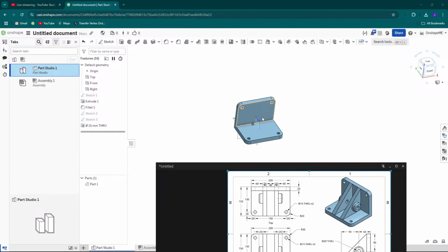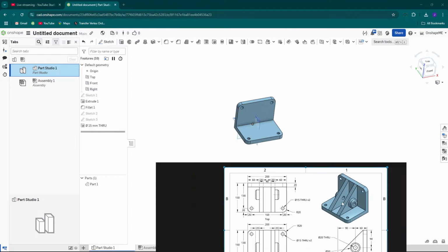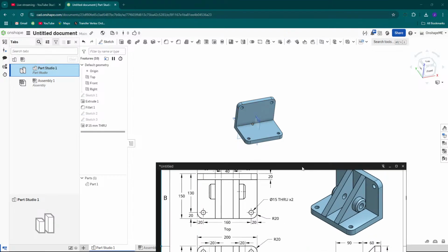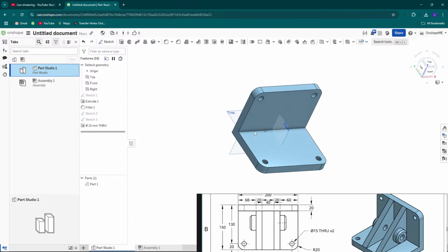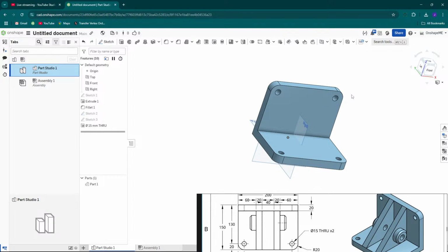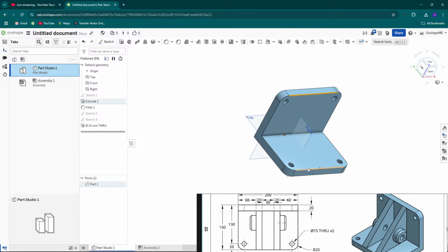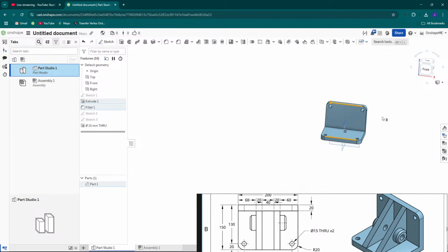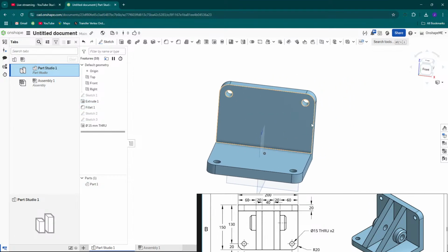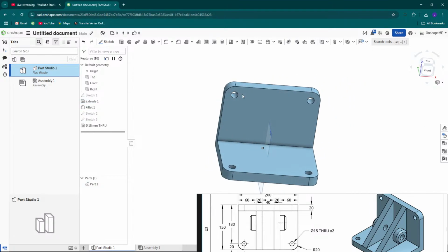After that, we will now create these 2 ribs. To do that, we will use another approach in which we will add plane coplanar to these 2 edges or these points. To do that, we need 3 points here, here, or here.